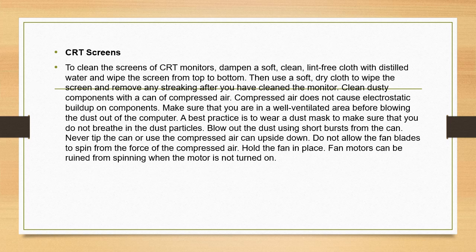Make sure that you are in a well ventilated area before blowing the dust out of the computer. A best practice is to wear a dust mask to make sure that you do not breathe in the dust particles. Blow out the dust using a short burst from the can. Never tip the can or use the compressed air can upside down. Do not allow the fan blades to spin from the force of the compressed air. Hold the fan in place. Fan motors can be ruined from spinning when the computer is not turned on.